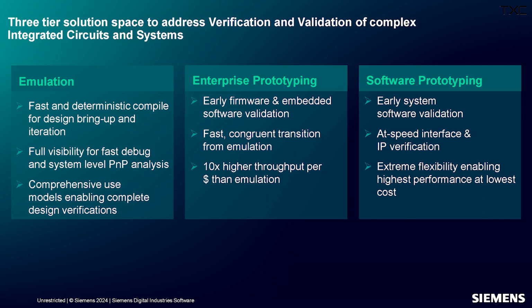This is close to architecture, where you have also a link to virtual platforms. So you make decisions on what architecture you're going to select, IP selection, and you start to assemble your SoC RTL. At that time, this is very heavy in compilation and debug. A little bit less on performance because the RTL is not stable yet. So you need to compile very often, change the design, and debug the design. And that is really the requirement envelope of what the emulators that we are offering today are defining.